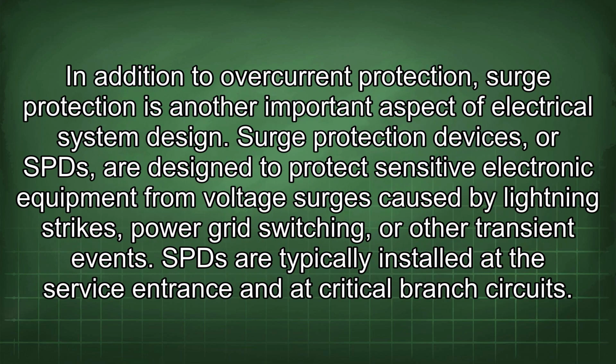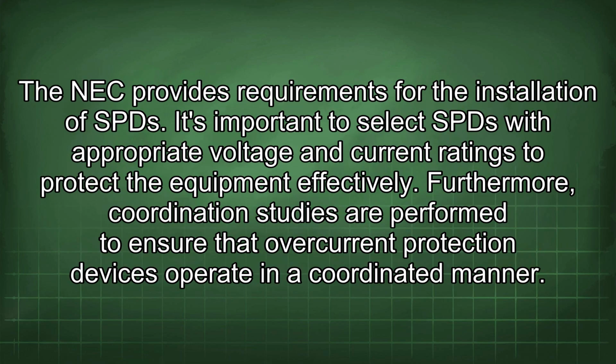In addition to overcurrent protection, surge protection is another important aspect of electrical system design. Surge protection devices, or SPDs, are designed to protect sensitive electronic equipment from voltage surges caused by lightning strikes, power grid switching, or other transient events. SPDs are typically installed at the service entrance and at critical branch circuits. The NEC provides requirements for the installation of SPDs. It's important to select SPDs with appropriate voltage and current ratings to protect the equipment effectively.